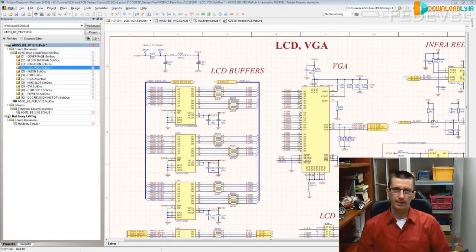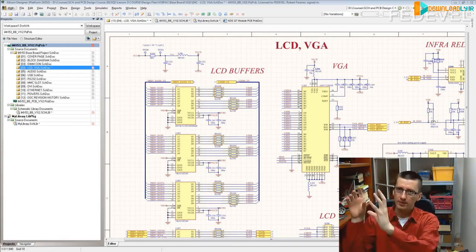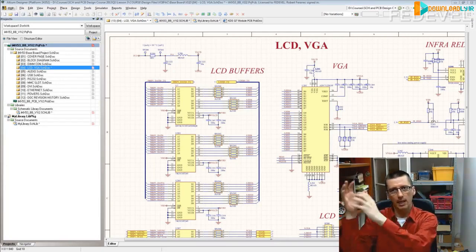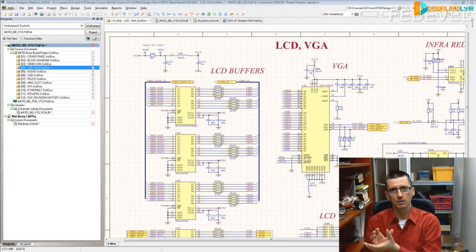At the very beginning of designing boards, I completely separated the ground and the powers and everything. When you had a look at the PCB, there was a visible gap between the analog audio and the rest of the digital part of the board.